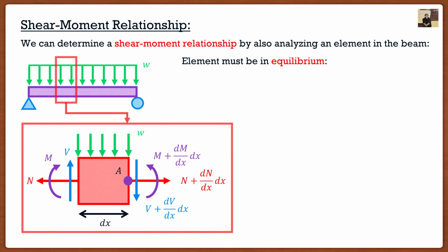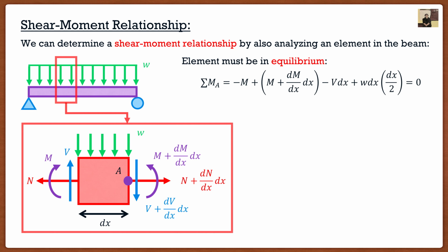So this is going to be on the right-hand side. Now, this is nice because the normal forces actually intersect through A. They're going to cancel out. It's going to become very nice and easy, but it's going to look gross. So brace yourselves. This is going to be pretty ugly to start. If I do the summation of moments about A, I get this expression right here. The key thing here is the shear forces have to be multiplied by the distances, and same with the distributed loads.